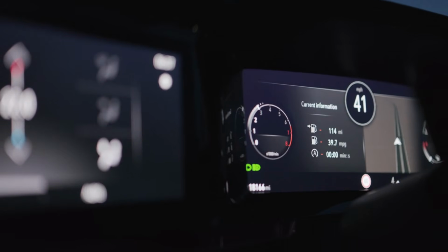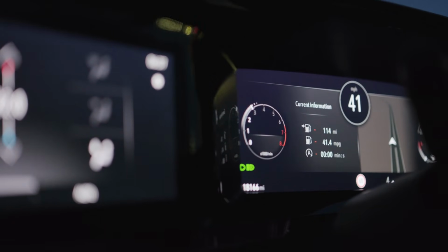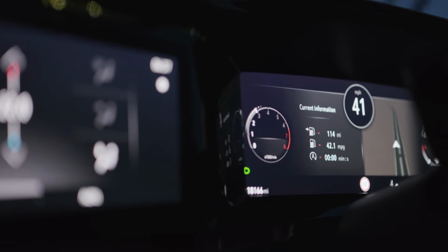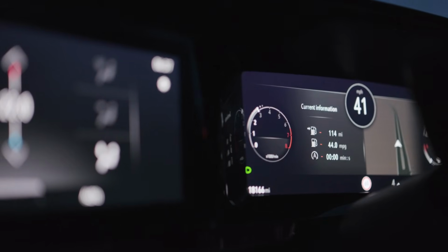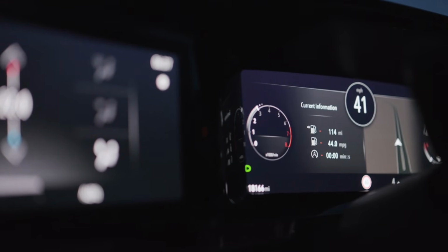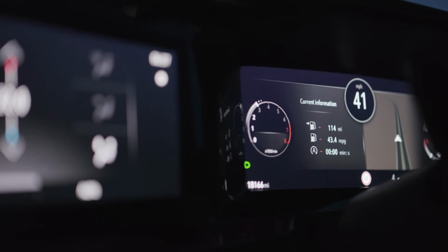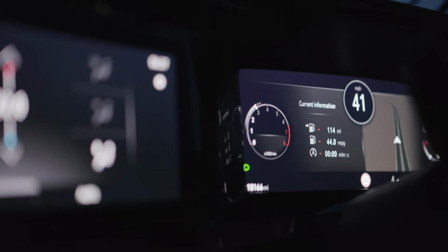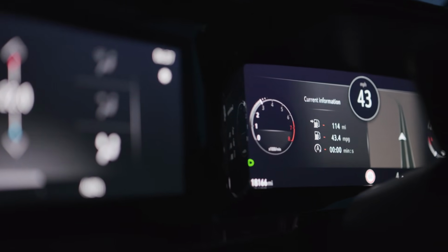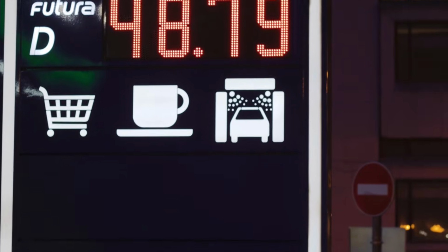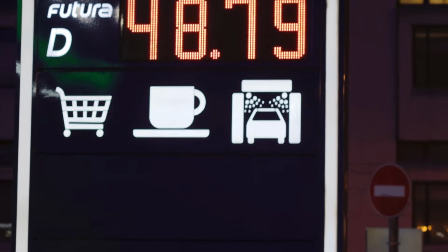The fuel economy translation of that correction is direct and calculable. If your engine was running at positive 15% long-term fuel trim, it was consuming roughly 15% more fuel per combustion cycle than stoichiometry requires. On a vehicle averaging 30 mpg under that condition, the corrected fuel economy after the MAF service should be in the range of 33 to 34.5 mpg, depending on driving conditions, load, and how completely the ECU adapts.